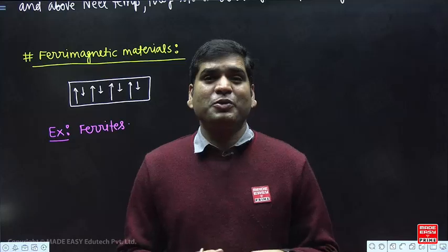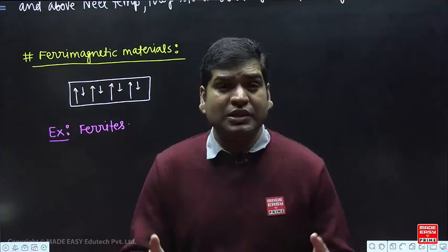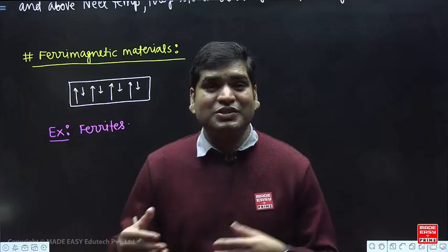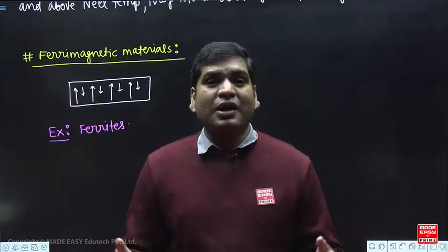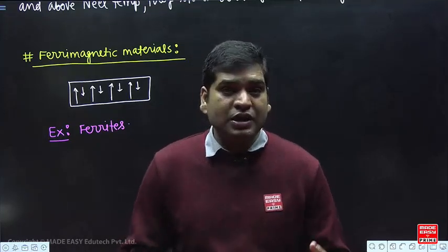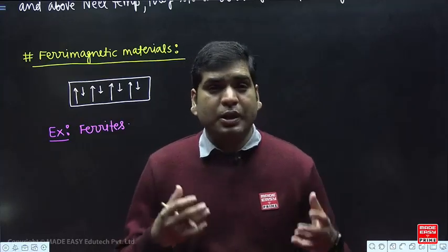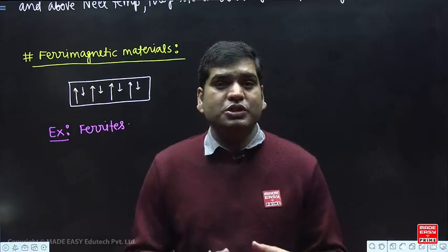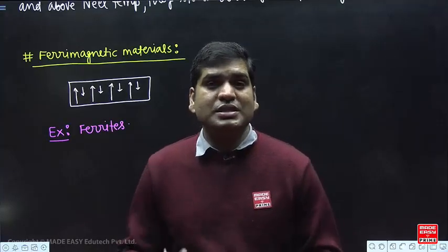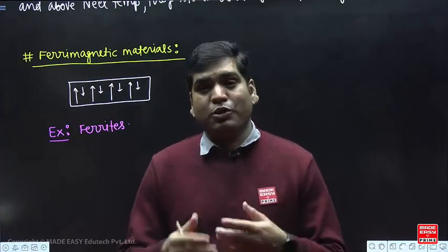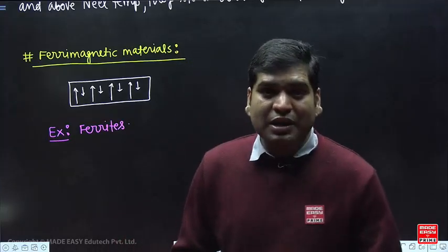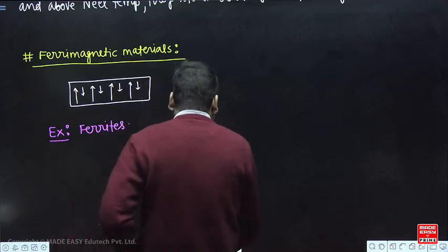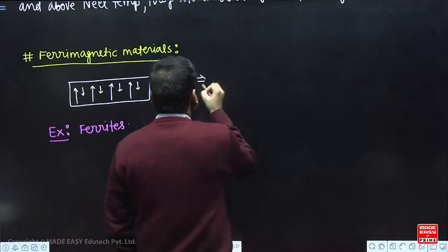At high frequency, ferromagnetic materials will produce very high loss because core losses are directly proportional to frequency, basically square of the frequency. So at high frequency, losses will become very high. So to reduce those losses, we are not left with any choice other than using these materials. So at high frequency, we will be using these materials as a substitute of ferromagnetic materials in designing core of transformers or inductors. So please note down, these materials also contain